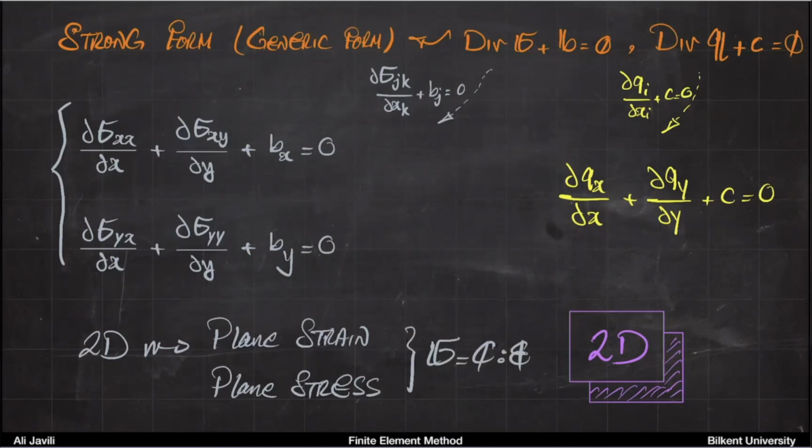But we usually talk about plane strain. Okay, so we assume the third dimension is fixed, so there is no strain in the third direction. It's like a plate that you fix on top and the bottom. But it doesn't matter in any sense or in any way. The finite element procedure, the question, everything is the same. Only when you use your constitutive assumption, you need to be careful which one you are using, because the meaning of the material parameters for plane strain and plane stress, they slightly differ from one another. Okay, but this is it.